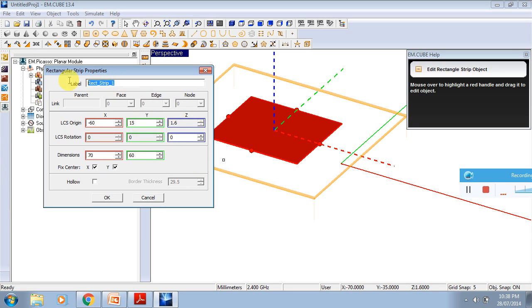Here you can enter the label of that rectangle. I am now entering RMSA as a label. Here are the dimensions, which is this is a length. I am entering 29 mm as the length and 38 mm as the width.